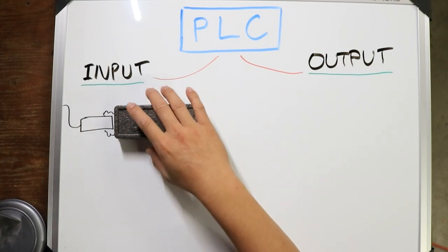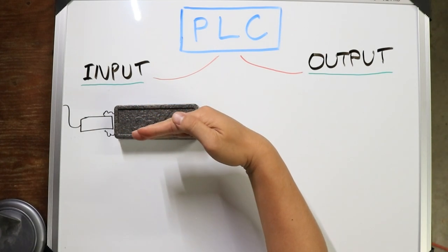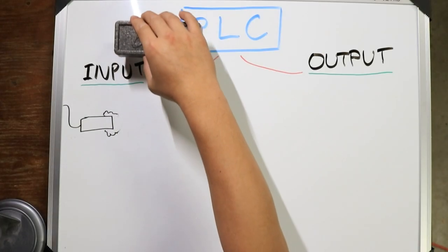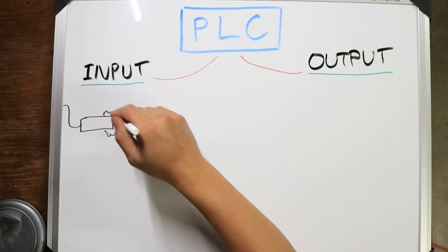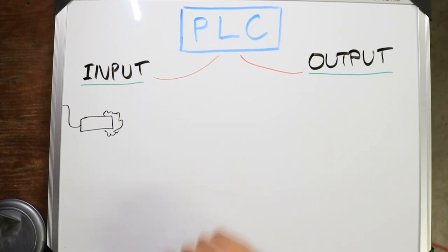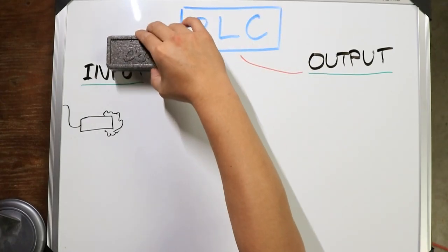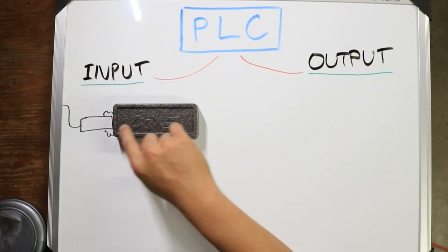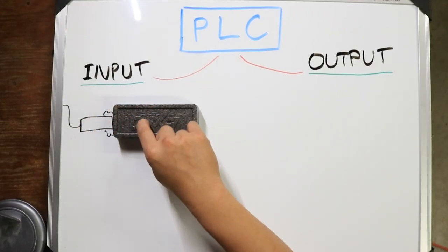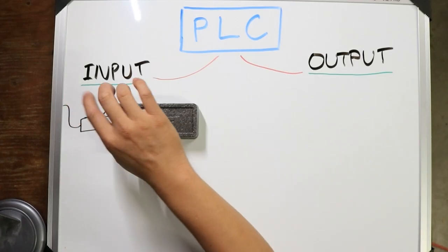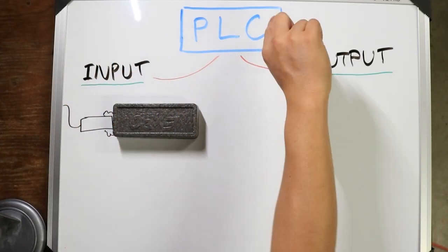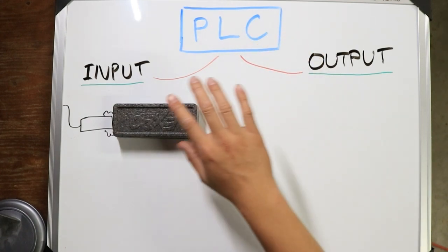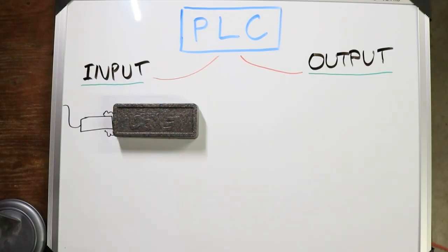In this example, we'll say that when a pallet gets to this position, we want the conveyor to stop. Currently it is off. The conveyor is running. Nothing's happening. Boom! It breaks the proximity, the magnetic field. Once it breaks that magnetic field, the sensor changes states, and that sends a signal to the PLC. Now the PLC reads it, sends the output telling the conveyor to stop, and now this pallet will stop right here where it is.